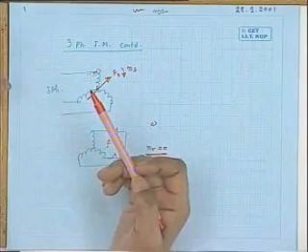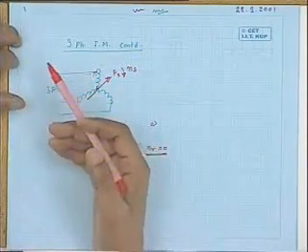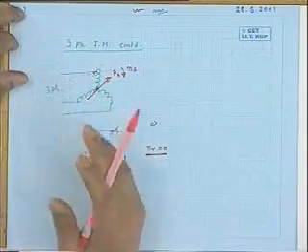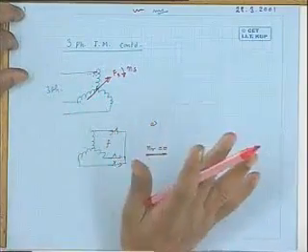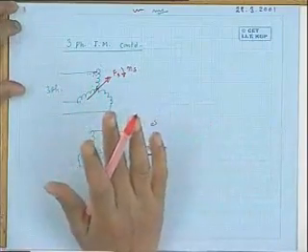This additional current will produce another rotating MMF, and it will draw that current in such a way that it counters the rotor MMF, such that once again the flux per pole remains the same in the machine, as decided by the no-load magnetizing current. Just like a transformer, it will happen.